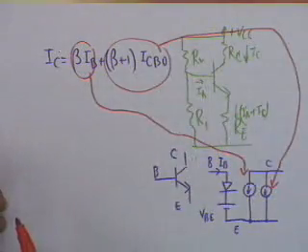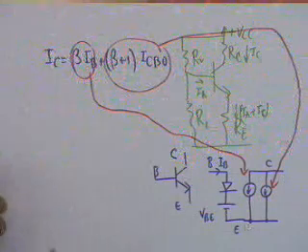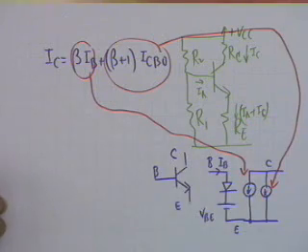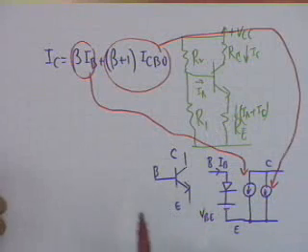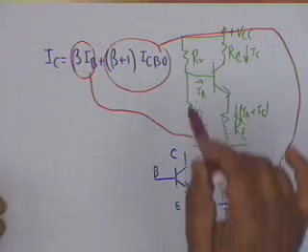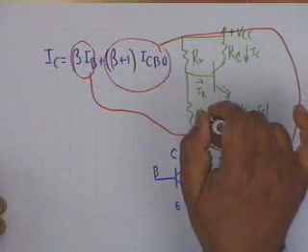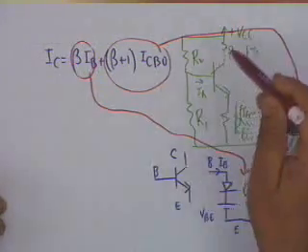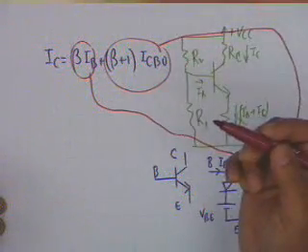Okay. This is the equivalent circuit that we shall use for quantitative analysis. For quantitative analysis, we shall also use a simplification. You see, this branch consisting of R2 and R1 and VCC can be separated. That is, you can include another VCC here, it does not matter as far as analysis is concerned.